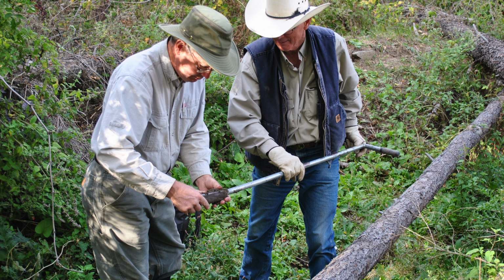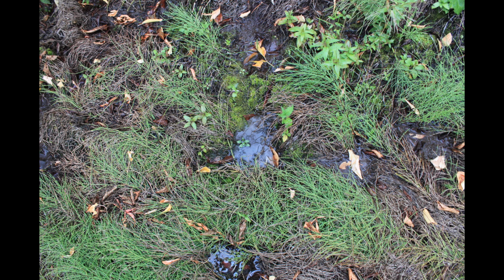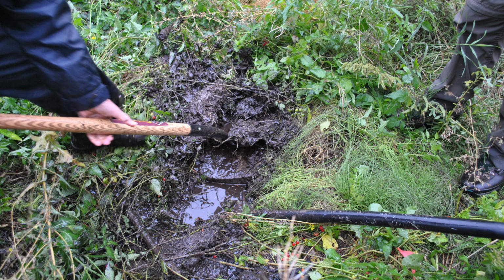We used a 2.5-inch diameter open-face clay auger to dig test holes at each area where we were going to design a wetland. The texture of soil near the surface was silt loam, and there was sand below the silt loam. Groundwater entered each test hole that we dug, and there were often small puddles of water on the surface of the ground. We found pipes buried in the ground in almost every wetland that we designed.